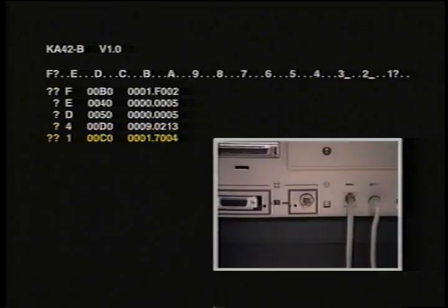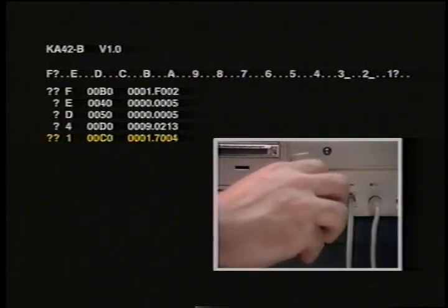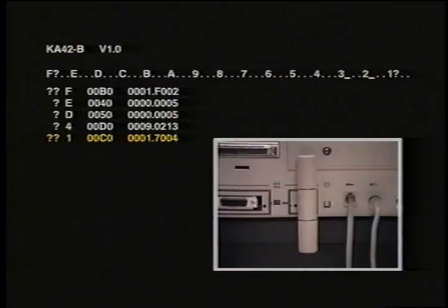One double question mark that is not a fatal error is caused by an absence of a loopback signal on the enabled Ethernet port. To fix this, either terminate the enabled port on standalone systems or properly connect to the local area network.